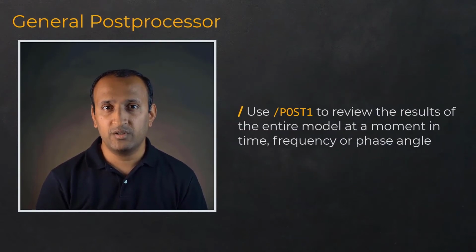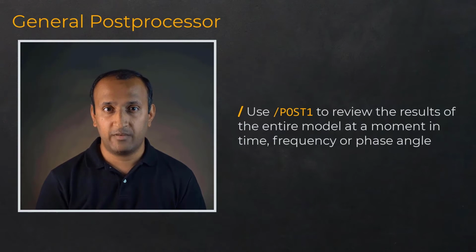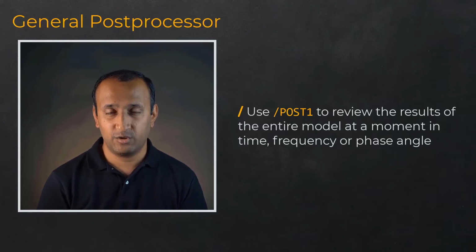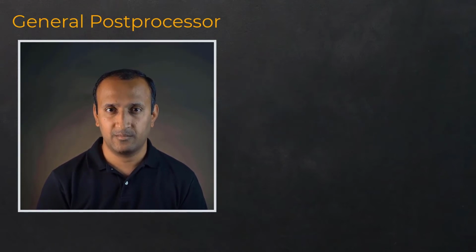POST1 is used to review the results of the entire model at a moment in time or at a frequency or phase angle. We use POST1 when we want to perform a detailed investigation over the entire model, such as determining where high stress regions are. If you have a linear static analysis with solution available at only one time, then we rely solely on POST1 to post-process the results.